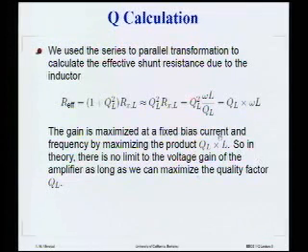So if you're looking at different inductors and you're interested in maximizing the gain, you shouldn't just look at the quality factor squared, as this expression is a little bit misleading. It really is just proportional to the quality factor. And so what about L? Why am I not free to use just any value of L?